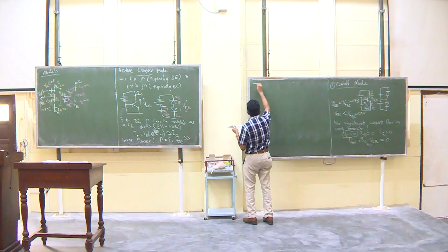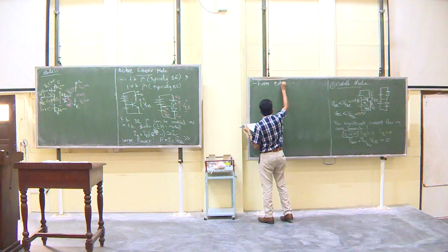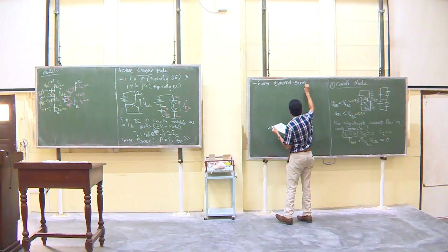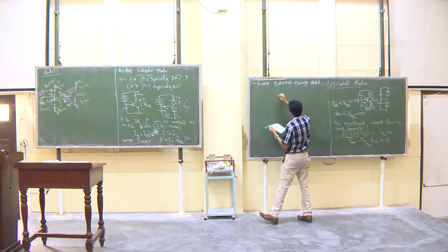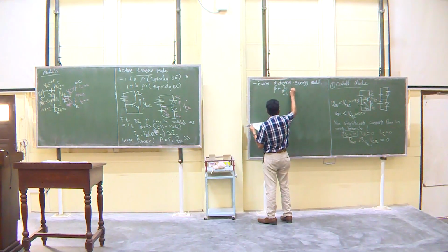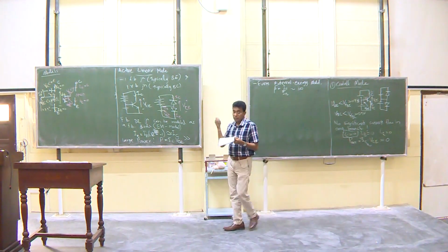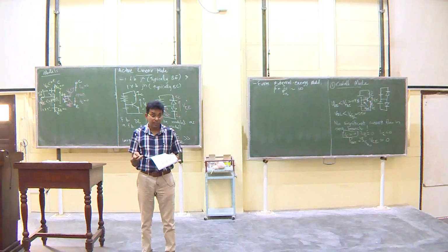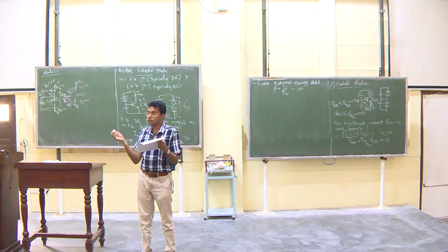So, from the external model, beta equals IC over IB is roughly about 100. This value 100 actually varies with temperature, it is highly sensitive to temperature, but in our model we do not capture it.